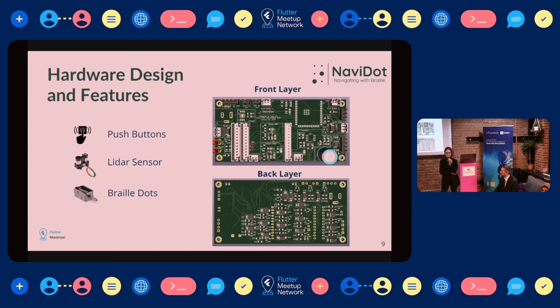Yeah, so basically we had the choice between Bluetooth and Wi-Fi for the connection with the device, pairing the device with the app. Wi-Fi consumes a lot of power compared to Bluetooth. So we're using BLE, Bluetooth Low Energy, in terms of battery consumption. If we used Wi-Fi, I don't think the device would have lasted more than an hour or so, but with Bluetooth we have about 3 hours of autonomy.